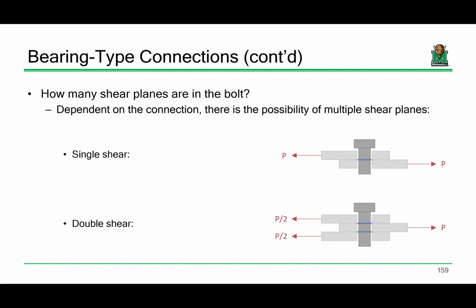That's a good question. The answer is no. But filler plates can affect slip capacity, the friction. And you're going to see a variable about that here in a little. When we talk about slip critical connections, you're going to see a variable on filler plates. So if you had a weird gap between 2 flanges, like 3/16, and you met that by using 2 filler plates, then you can have a reduced slip capacity as a result. And we'll look at that here in a little bit.